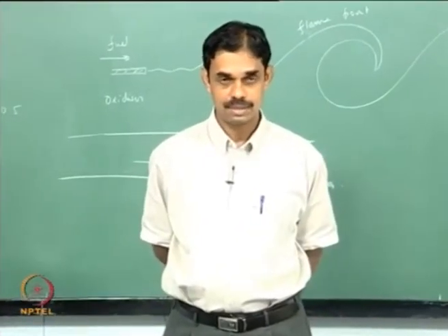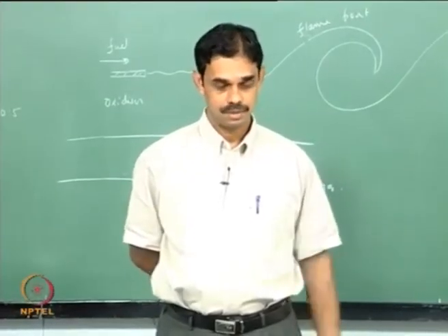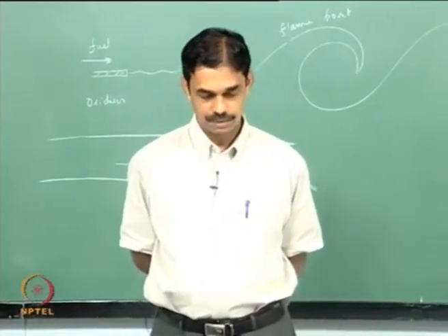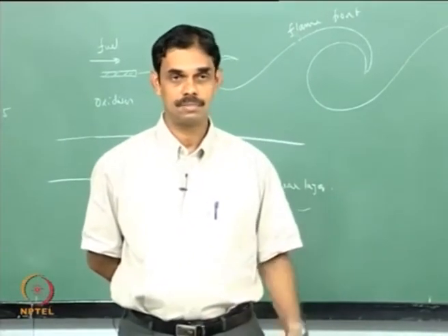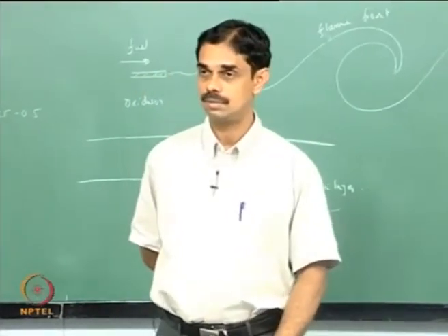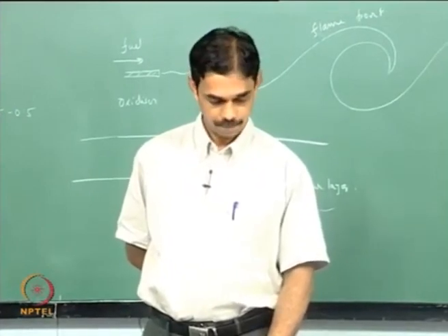So whether oscillations are excited or not depends on whether the net driving is more than net damping or not. Everything goes by what Rayleigh said. If the heat release is in phase with the pressure oscillations, you have acoustic driving. If they are out of phase, then you have acoustic damping.